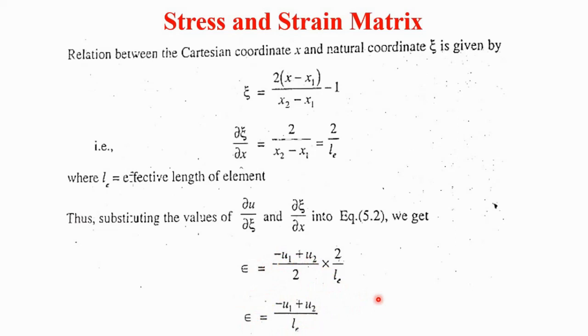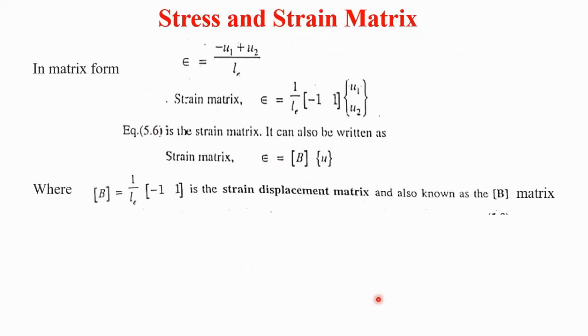Then again, this equation of the strain ε is equal to (−u1 + u2)/le. We can write this equation in matrix form.